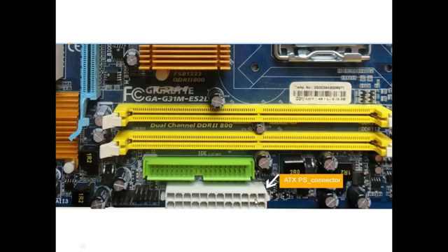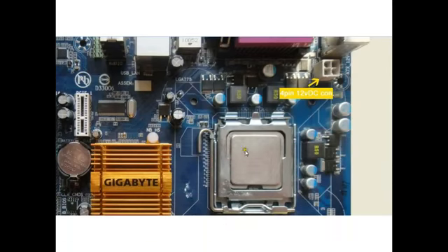Here comes the power supply connector, the ATX PS connector. ATX stands for Advanced Technology Extended. 20 or 24 pin connectors will be there. Through this connector we give the supply to every part of the motherboard except the CPU. The CPU draws its required voltage from the VRM section, and the VRM section is fed with 12 volts. This we call a 4 pin 12 volt ATX connector.